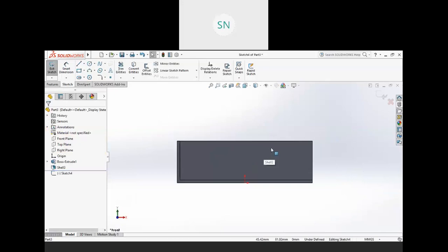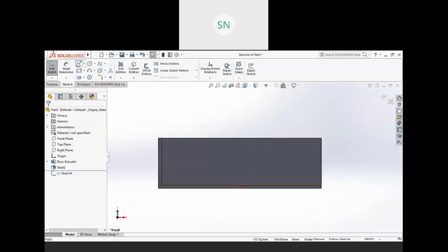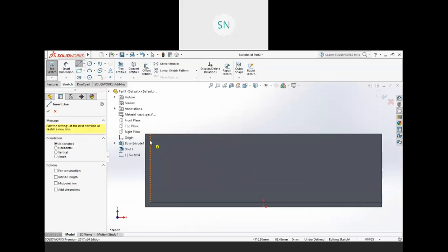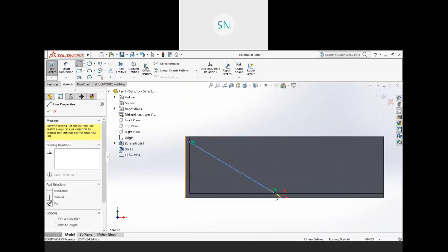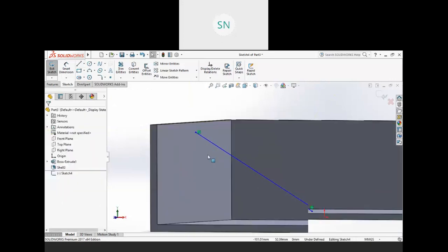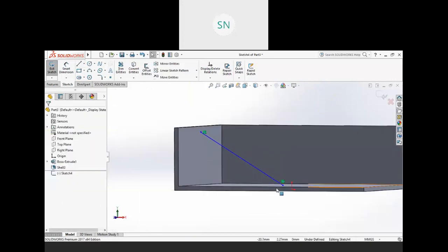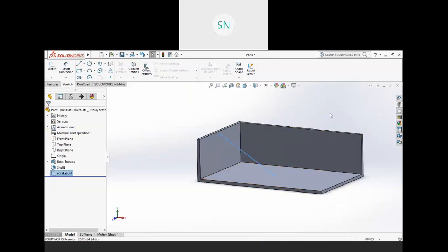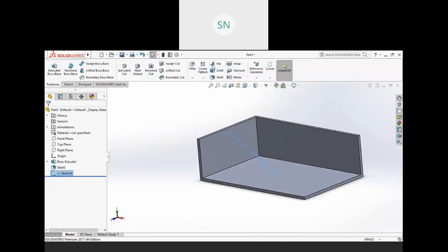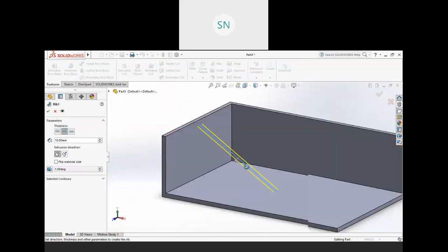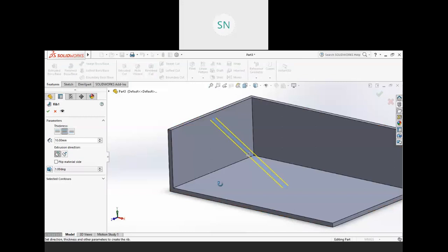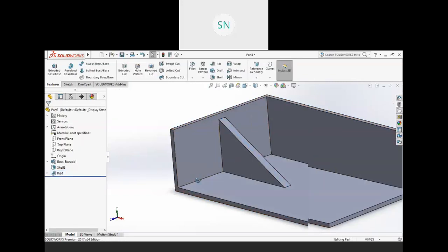There are many restrictions and constraints that you have to remember. Actually, there is one main thing. Whenever you create your sketch, it should be properly constrained, properly connected, and then finish it and go to the rib tool. So this rib will create a support of solid geometry, and you will get this type of preview, and our material is going downward. Then just hit OK and you will get this rib,